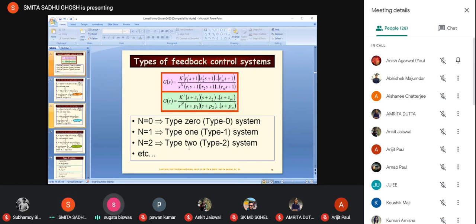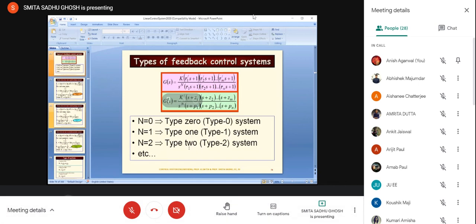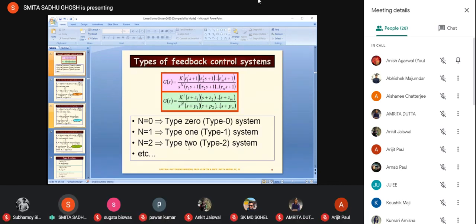Why are we taking the open loop transfer function? Why not the closed loop transfer function? We'll come to that, because in error analysis, G(s) is what is going to be considered. We will find that G(s) will be the important thing to be considered. So that is why we are interested over here. Of course, we are speaking of only the terminology, but why it is of interest, we'll be coming to in a moment. We'll see that in error analysis, the open loop transfer function is the all important thing, irrespective of whatever else happens, right?